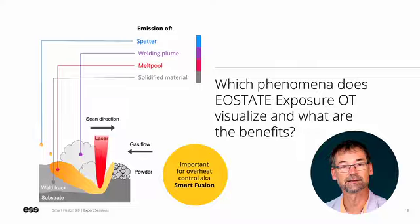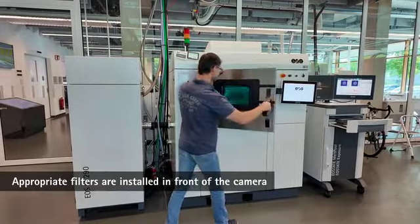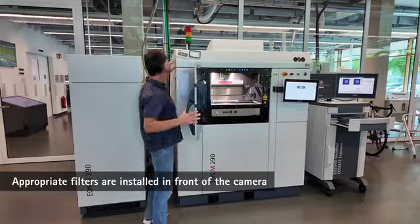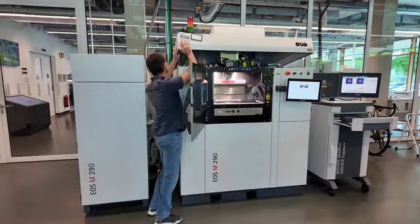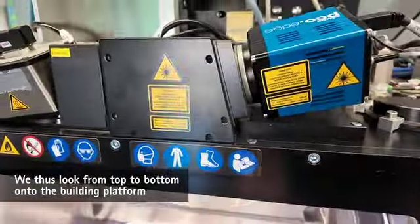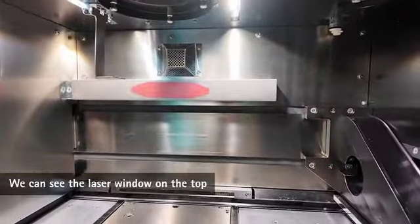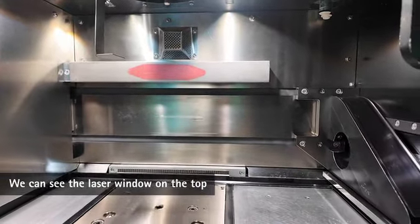All of these signals are recorded and combined into one image, the OT integral image. We don't measure purely thermal radiation, but the radiation intensity in the 900 nanometer range, which is made up of the emission spectrum of spatter, welding plume, the melt pool and the solidified material.